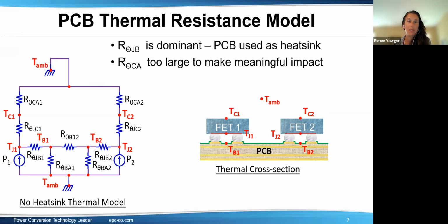Can we use Kapton insulation tape as filler between the heatsink and the GaN surface? So in other words, a heatsink up here, and you put Kapton tape on. Yeah, I think the answer is yes. I'm not sure about the thermal conductivity of Kapton tape, but just a point of trivia: on the bottom, if you look at the bottom of GaN FETs, they look kind of orange.